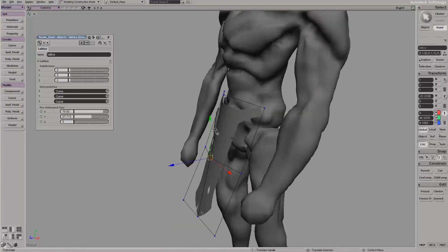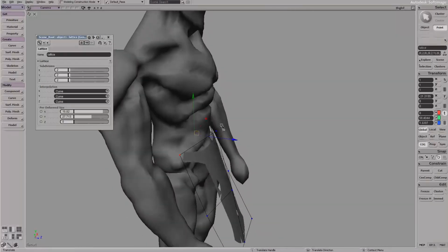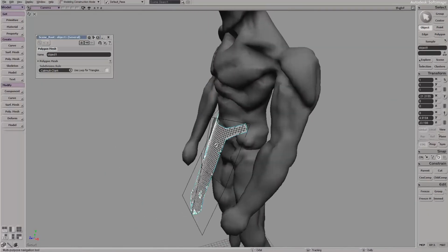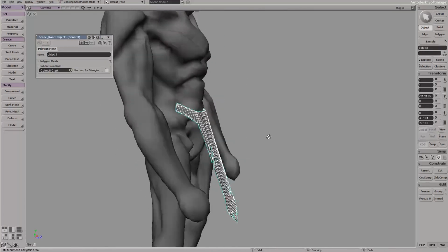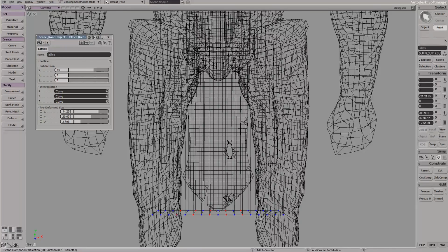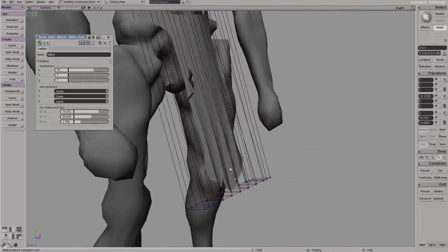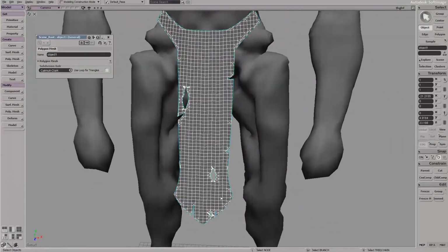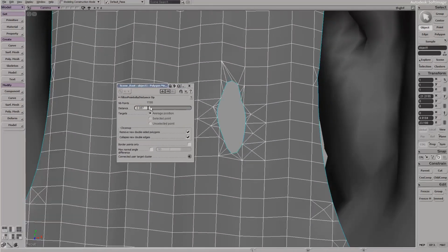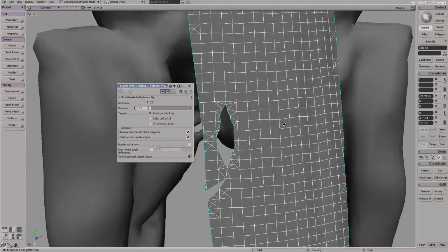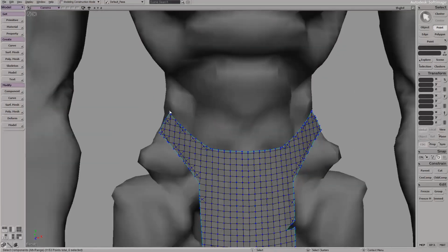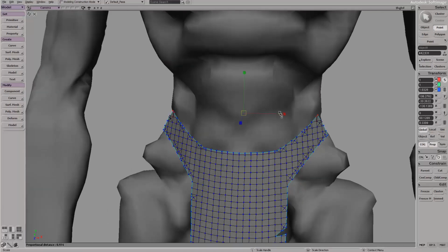And I'm doing this first pass alignment of the cloth to the body of the robot character using a standard lattice tool, which, let's say if you're using 3D Studio Max, would be the FFD tool. I'm also adding these initial folds to it to give more of a sense that this is a flexible fabric or cloth material. Here, I'm doing things like filter edges, which reduces all the redundant edges or points to reduce the polygon count and make the geometry a little bit cleaner.